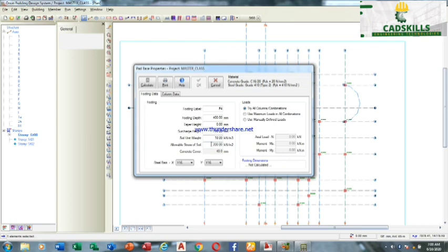Right? So the lesser the bearing capacity, that means the type of foundation changes. If the bearing capacity is too minimal, you are to choose another type of foundation, either pile or raft. But if the soil bearing capacity is good enough, then you go for pad. Right? These are the factors that one needs to consider before choosing the type of foundation to be used for his building or structures.